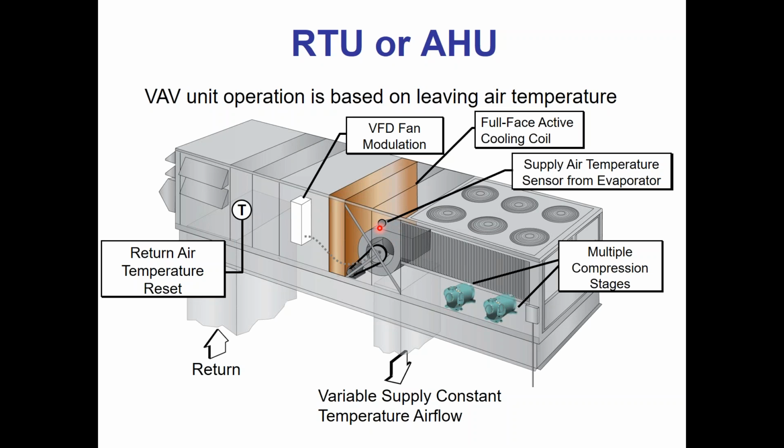It's usually going to be mounted on the inlet of the fan because most of the time the fan is a draw-through, meaning it's pulling through the evaporator coil. If I put it right at the coil, I could have some inaccurate readings. I want to be a little further downstream, once the air is fully mixed. So putting it over towards the evaporator fan is typically what's done. I could also put it down here in the supply duct if I chose to.